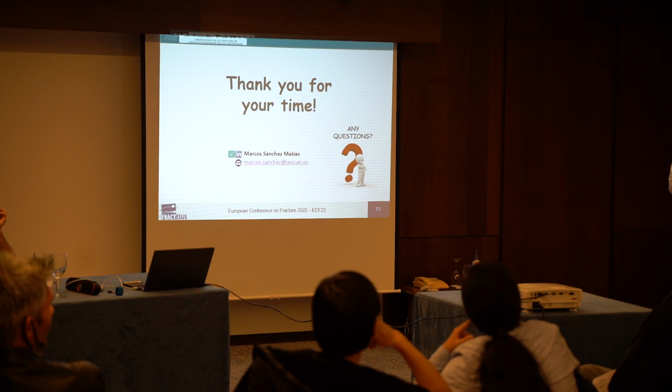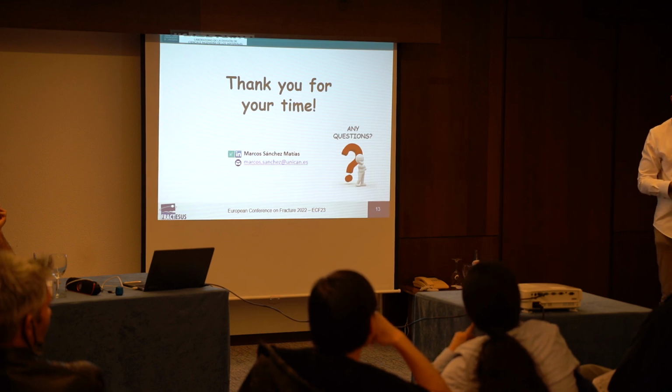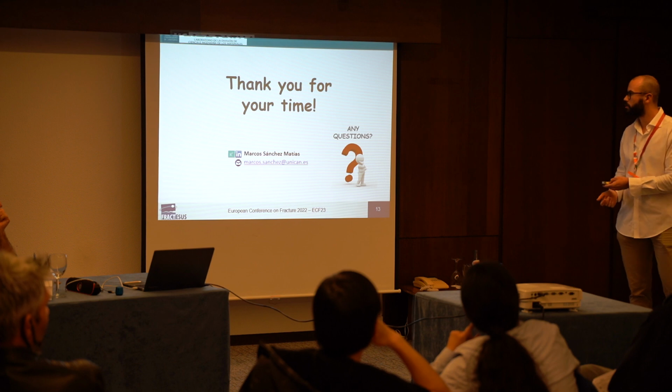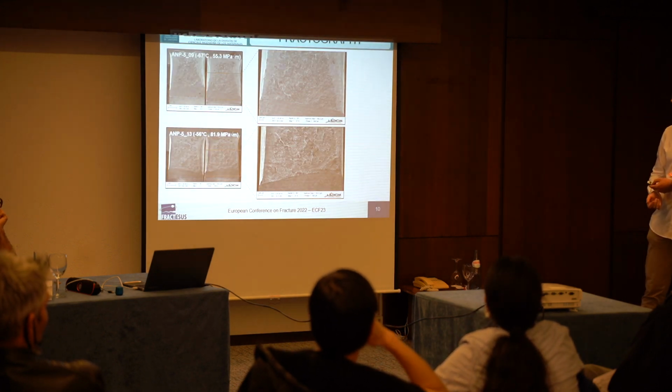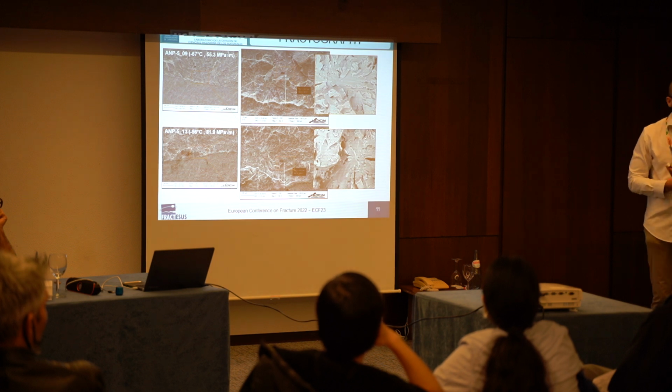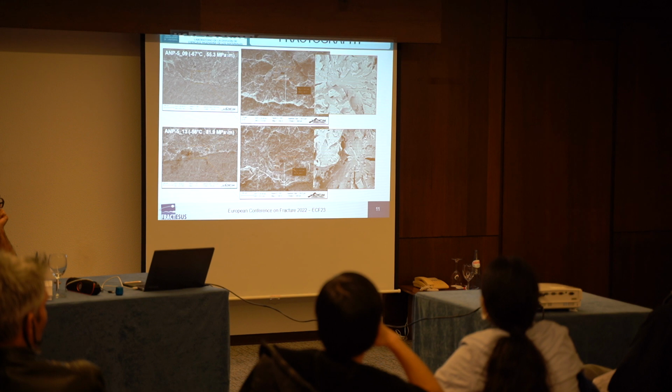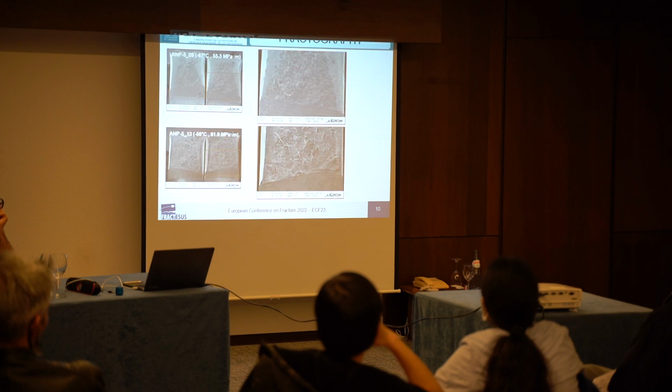From your fractograph, if you look at the crack front, you're talking about fulfilling the criteria for crack front straightness. It doesn't look like it, you can see it's preferentially going to one side. There was no pre-compression, okay. At the same time, we've done tests on mini-CT of exactly the same size, but we've tried to use side grooves.